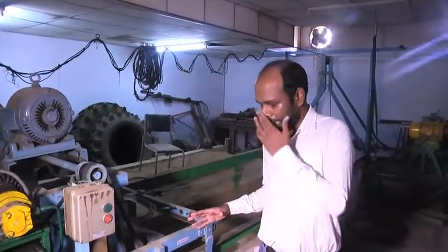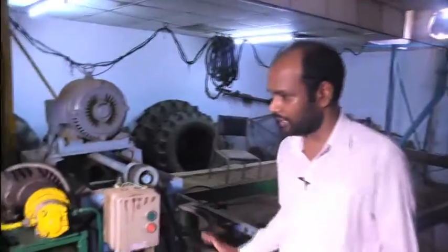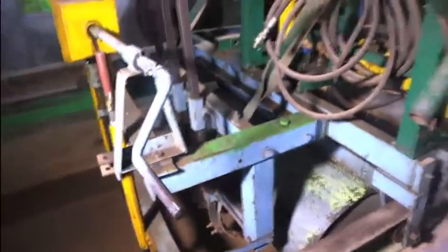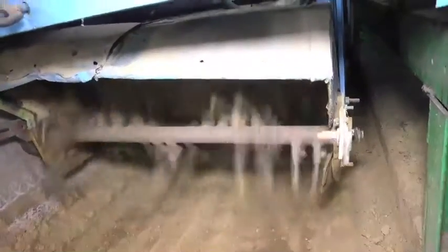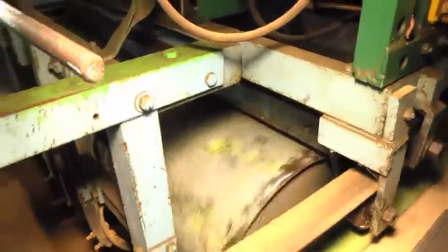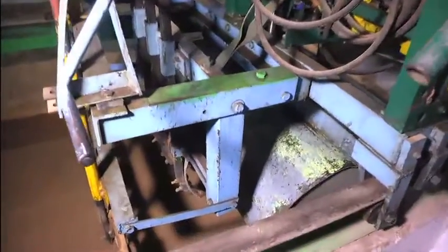Well, as explained by Professor V.K. Tiwari and my friends about the soil traction laboratory of IIT Kharagpur, I am going to explain to you about the processing trolley. With the help of this processing trolley, we are preparing the soil of different strength levels. For preparation of soil, this processing trolley consists of rotavator, leveler, cultivator and roller. With the help of the rotavator, we are tearing up the soil, with the leveler we are leveling the soil inside this soil bin, and with the roller we are compacting the soil at different compaction levels.